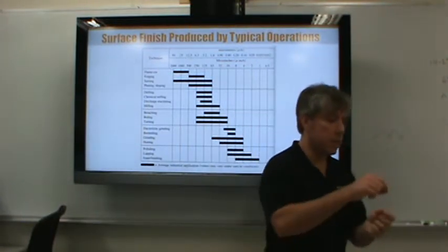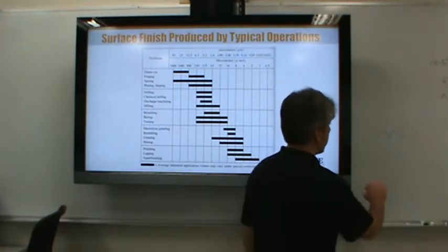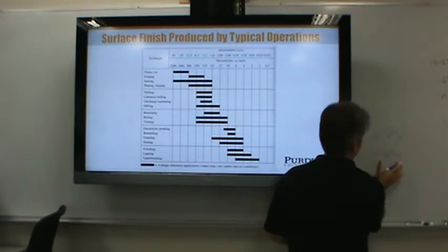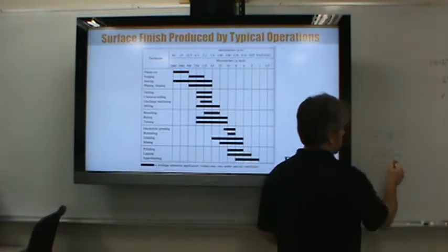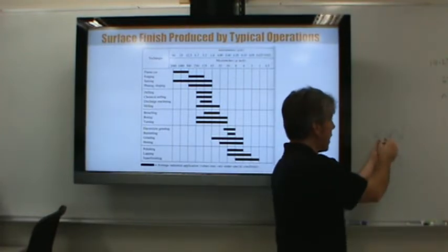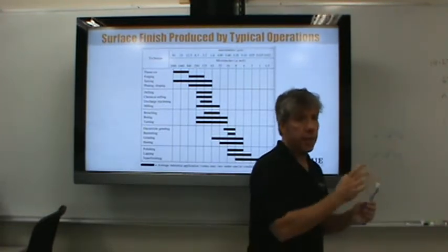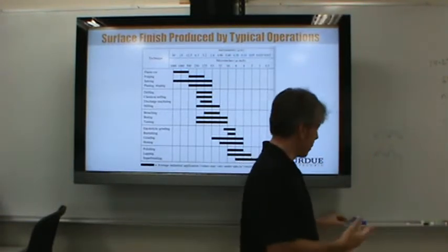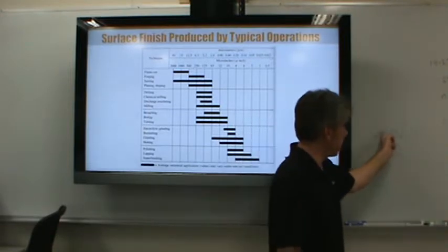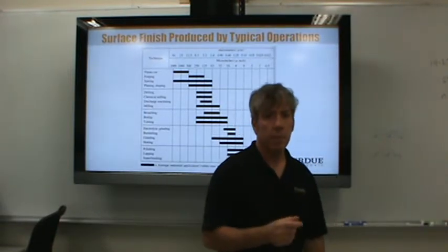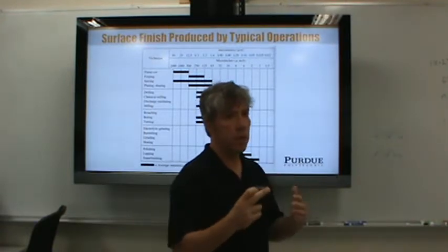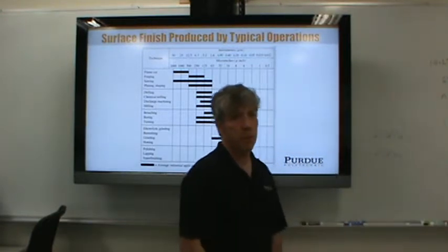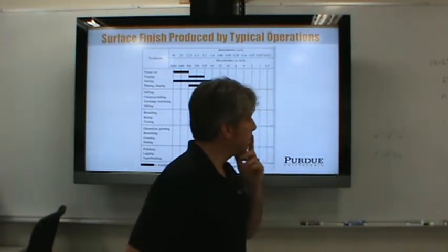So the way that works is instead of having an actual shaped part that they would drive into this, instead of having a part that they had to make that looked like this, that they would electro discharge machine it to blow out all this material, what they did is they used a wire running this way. A lot like a saw, they just ran that wire through the material to make the shape that was needed. And with CNC control, it's easy to make that shape. So they had a very fine wire, and they just ran it through very, very slowly, where the sparks from the wire to the workpiece blew away the material of the workpiece and cut out the part.